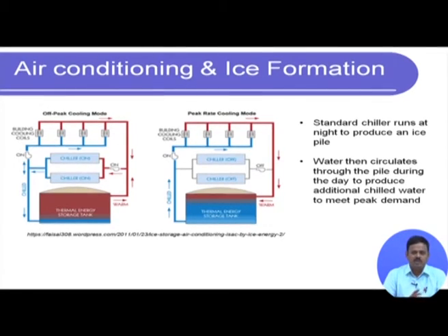So, what they are trying to do is use the very same principle, a thermal energy storage device as plug and play, which they at least claim you can plug into any refrigerator. When you have additional electricity or energy available, you can use it to generate ice, which can be used later, let us say during a power cut, where the chiller is off. In a power cut the chiller will be off, so use it for chilling in this manner. Clear? So, this is another example.